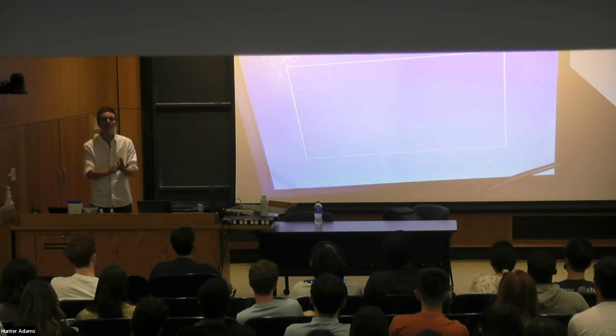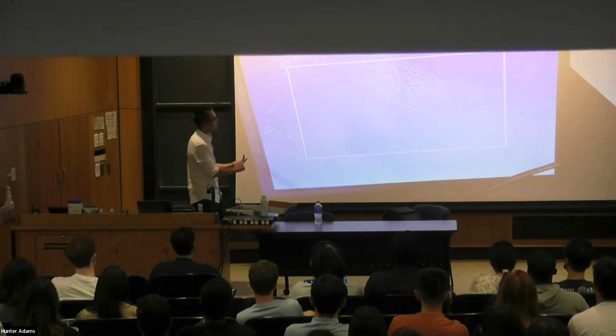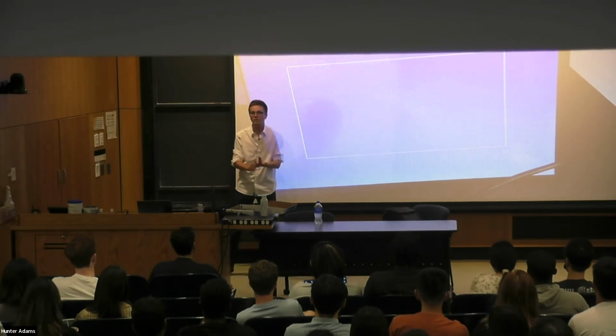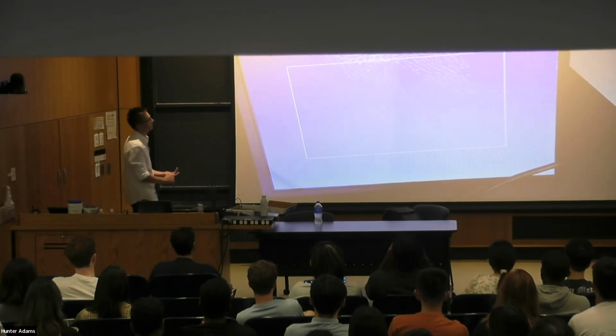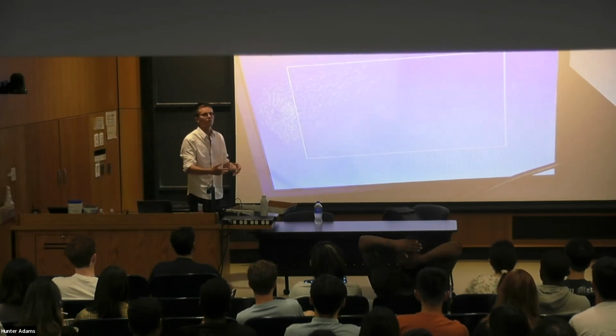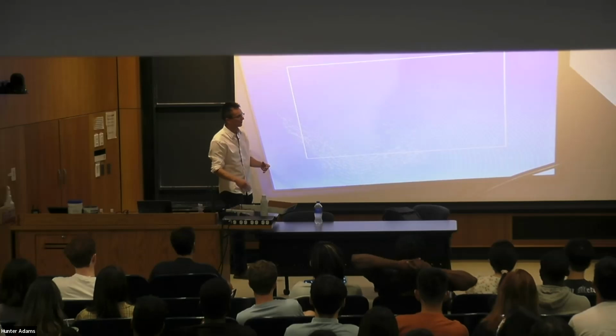Floating point isn't going to fly here, too slow. So we're going to talk about an alternative called fixed point, which allows you to use integer arithmetic, which is way faster than floating point arithmetic, but to maintain fractional resolution. We'll talk a lot about this.